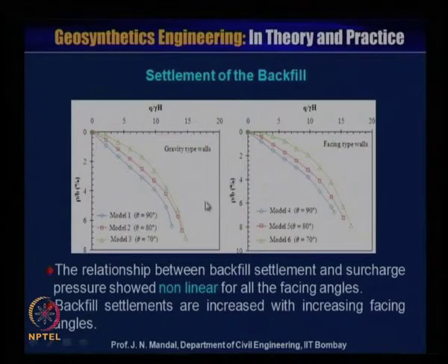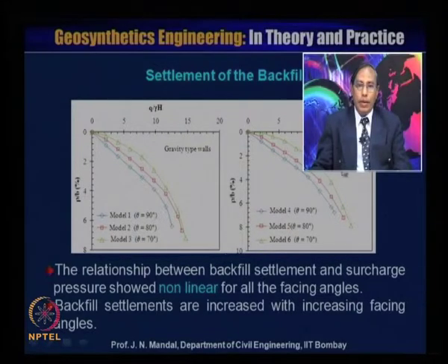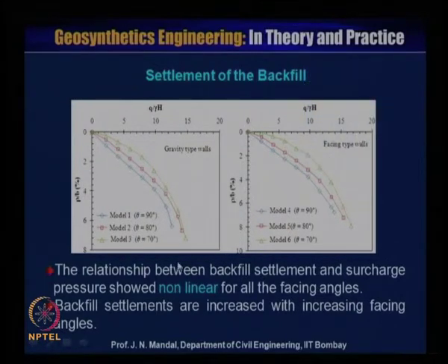The relationship between the backfill settlement and the surcharge pressure is non-linear for all facing angles, whether it is 70, 80 or 90 degree, it is all non-linear. The backfill settlement increases with increasing the facing angle.